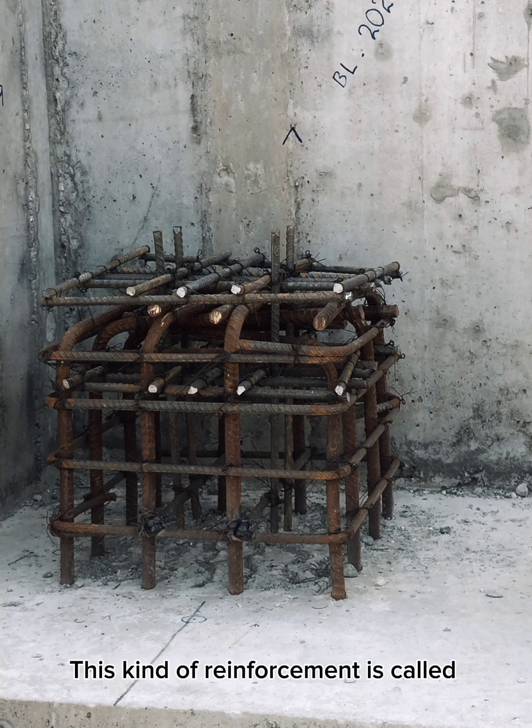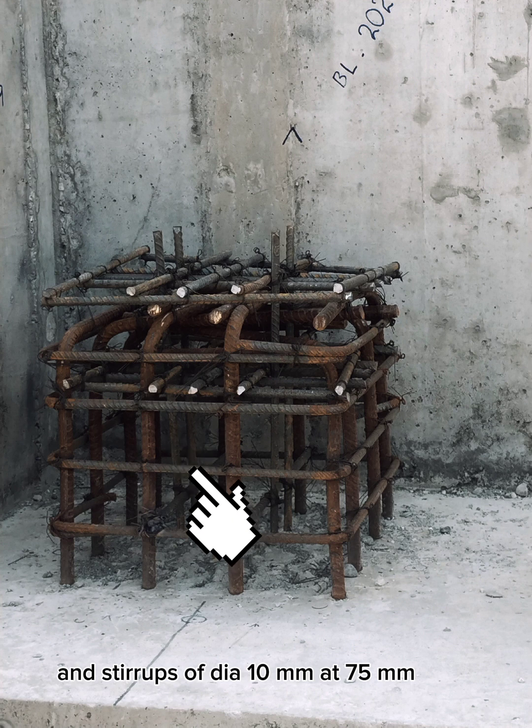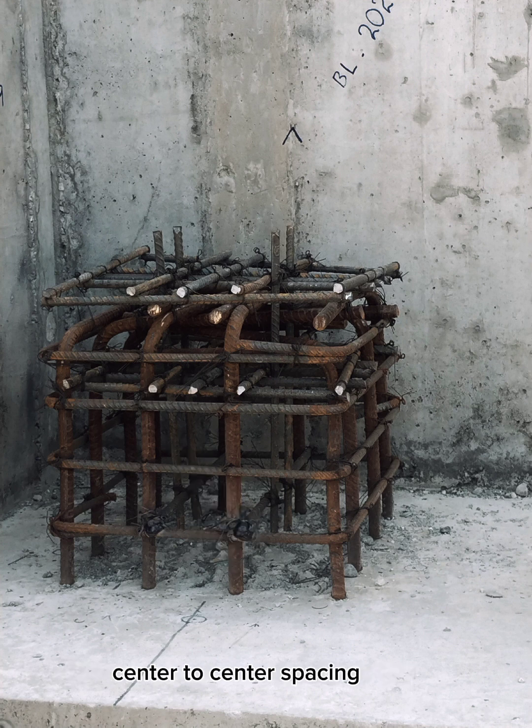The image here is a reinforcement cage of a pedestal at which the bearing will be placed. This kind of reinforcement is called the double mesh reinforcement. The diameter of the vertical rods are 16 millimeters, and stirrups of D are 10 millimeters at 75 millimeters, center to center spacing.